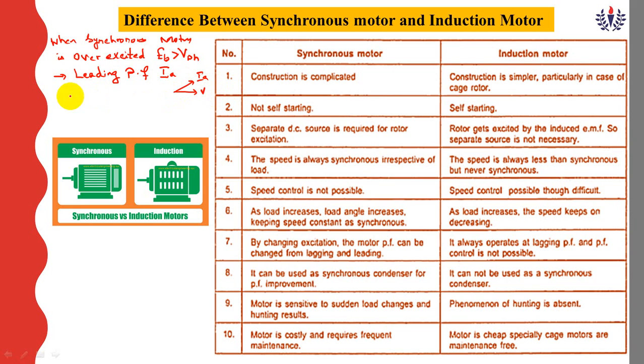If the synchronous motor is on no load, meaning we are not applying any load on the motor, then the load angle delta is very small. Because delta is very small, the power factor angle phi increases, up to 90 degrees.